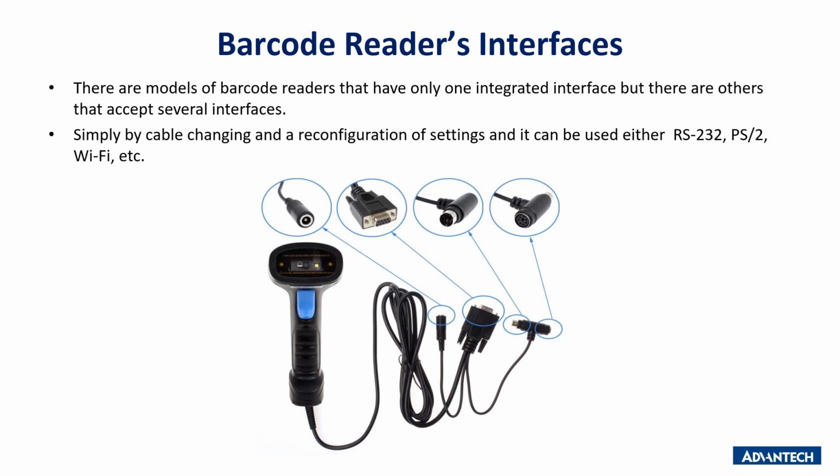Barcode readers interfaces. Usually, the barcode readers have only one integrated interface. However, there are other versions that accept several interfaces using the same cable, like in the below picture. Simply, by cable changing and a reconfiguration of settings, it can be used either RS-232, PS2, etc.